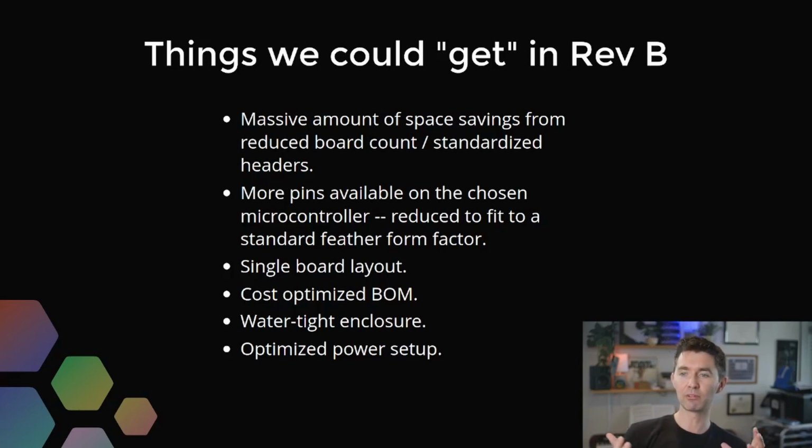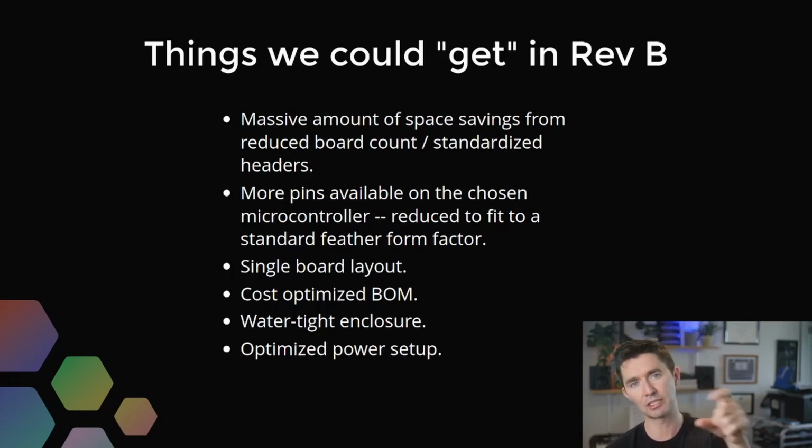So one of the big downsides to doing this sort of thing, using a dev board in this Rev A proof of concept kind of form factor, is that I use the nRF9160 SiP quite a bit, which has tons and tons of pins, but they're not broken out on the feather form factor. It's only got like 28 pins or something on it, so there's a bunch left behind. Again, that's a trade-off that I was willing to make, but I would get access to those and have more capabilities once I actually put the SiP down on the board. So that's an argument for doing that sort of thing.